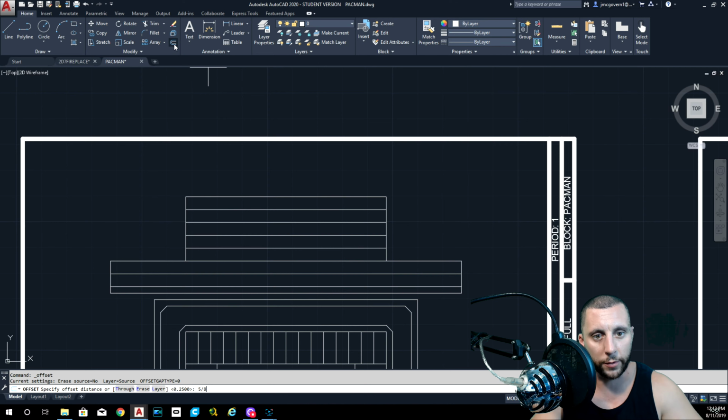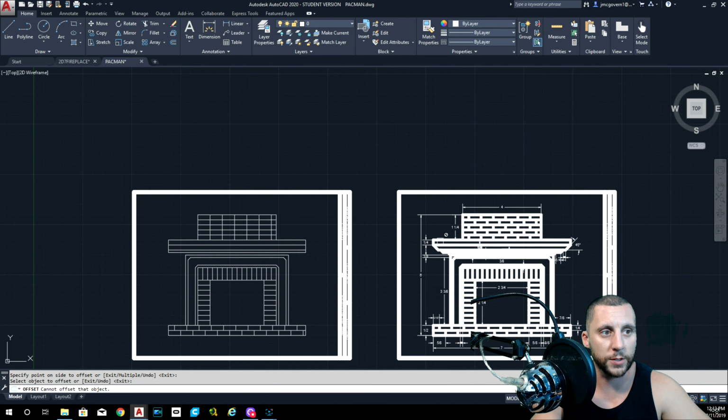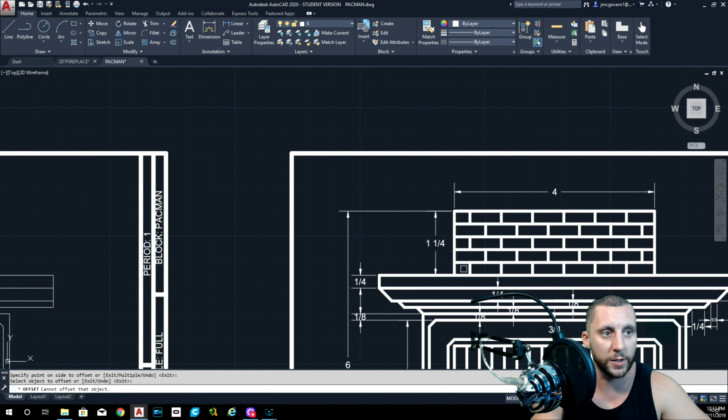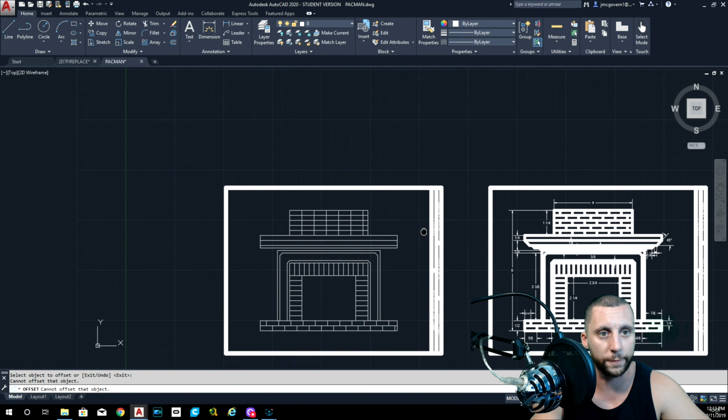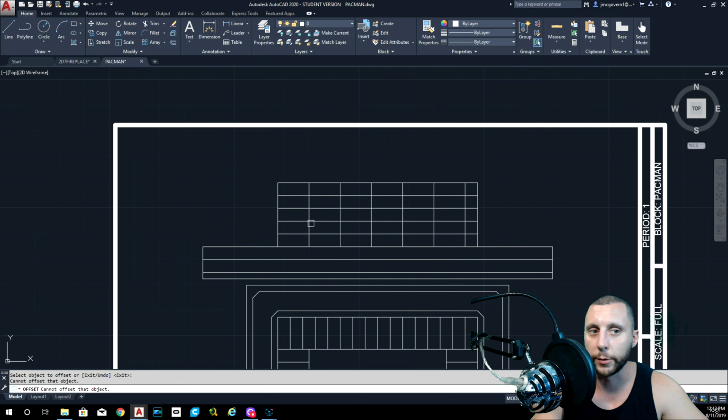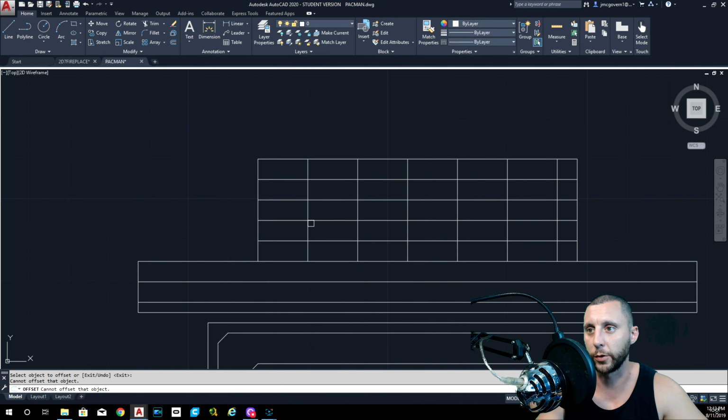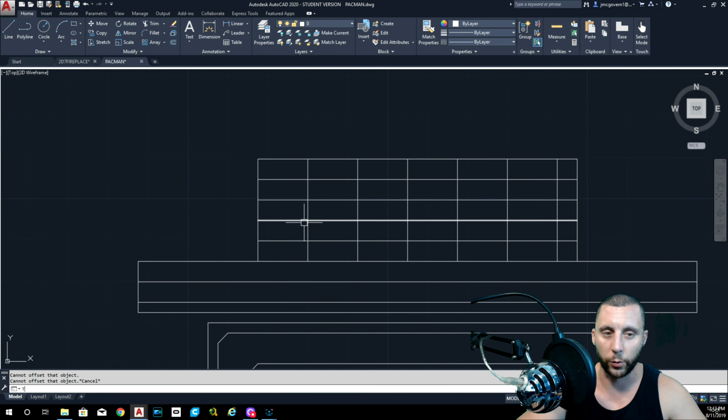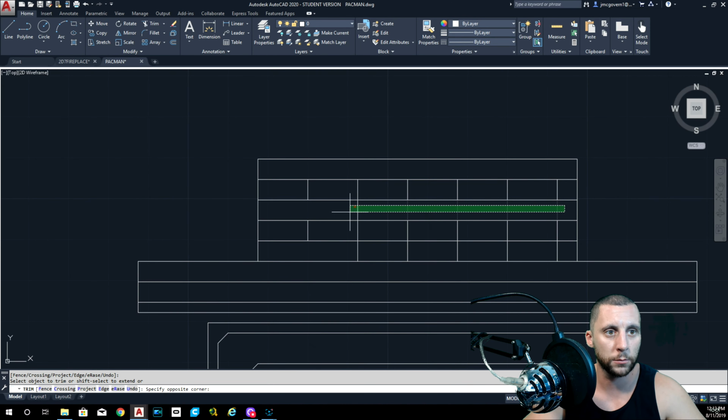So what I want to do is I'm going to do a 5/8 offset, and I'm going to go all the way across 5/8. And every other line, so you'll see that this first, the second one and 4th one start with a full brick. Does that really matter? Probably not, but I'd like it to be the same. If you're out there in the world and you're somebody else, do it the way you want. So the 2nd and 4th one, which means that I want to trim 1st, 3rd, and 5th. But you can do those all the way across like this. So those 2 rows are now good.